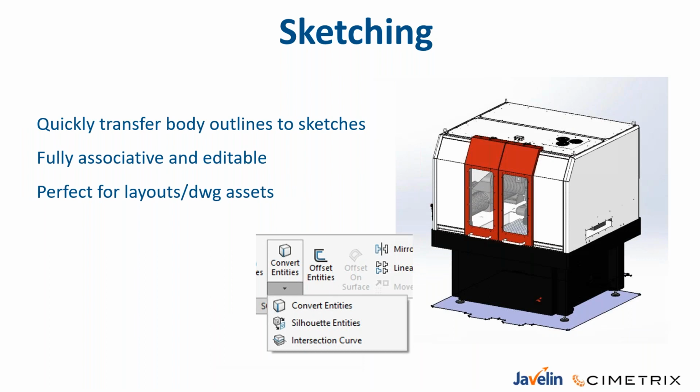Now, something in sketching that is going to allow you to really work better in low detail versions is the brand new silhouette entities command. So if you've ever used convert entities, it's a really cool way to select something and then convert that and project it onto your sketch plane. Well, now in SOLIDWORKS 2020, we have the ability to create outline sketches from bodies. So this is great for if you're working in layouts and things like that.